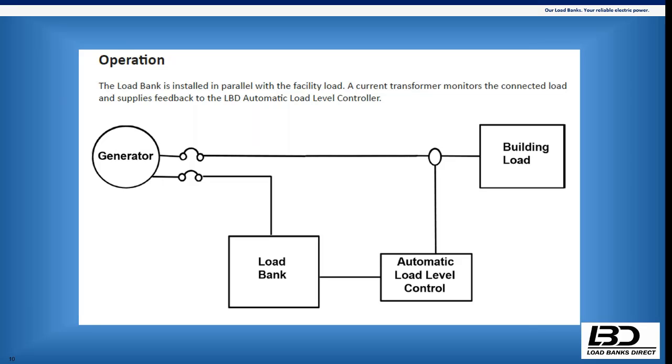On our end, it's like a $1,000 option. So from a cost standpoint, it's definitely a lot cheaper to keep your generators lightly loaded all the time than have to do a full rebuild because it gets all gunked up from wet stacking.